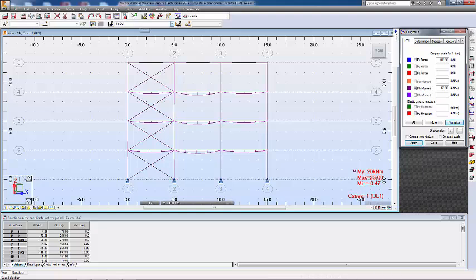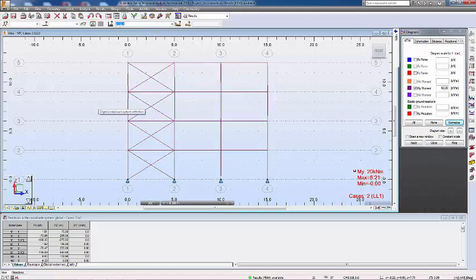And then for the lateral loading in this system, they have a very little bending moment inside the structure because the structure is pretty stiff, so they do not move too much, and the bending moment inside this one is pretty small, and so that's a combined effect. So it looks quite interesting. And compared to the one we had before, the rigid one, all the bending moments inside the structure are smaller.